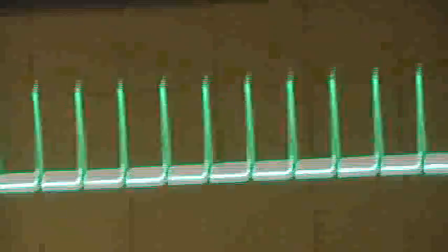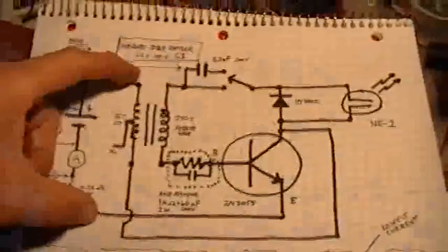Okay, and over here on this one we're at 20 volts per division with a 10x attenuated probe, so that's 200 volts per division. So right now it's showing slightly over 200 volt peaks there in that oscillation, and that's the output that's measured here with respect to the ground reference. Okay, and that frequency, I've computed it already, is about 43 or 44 kilohertz going across there. Sorry about the light.